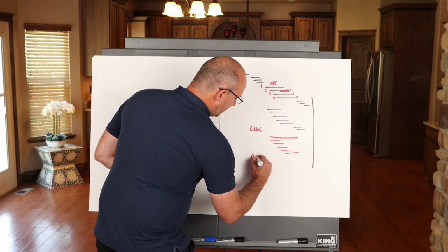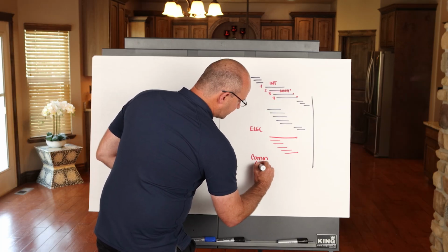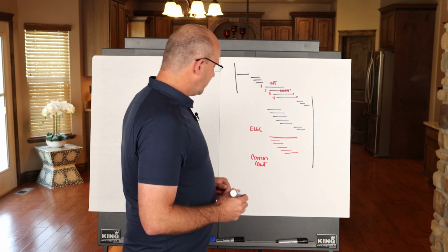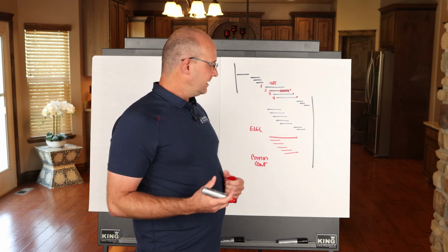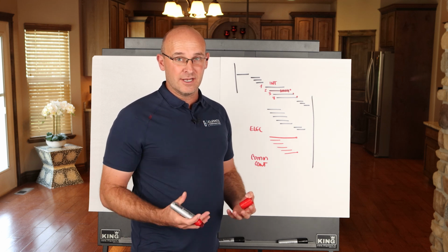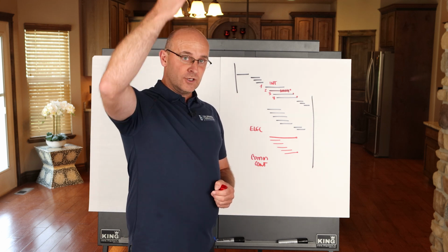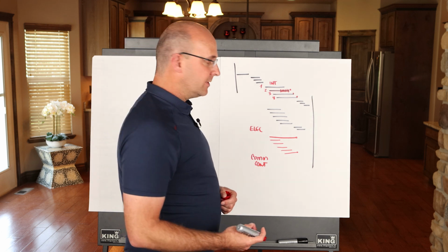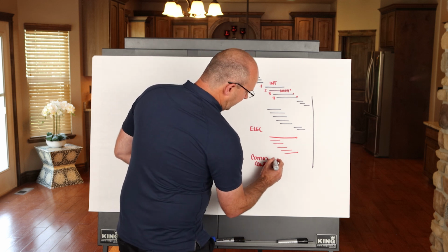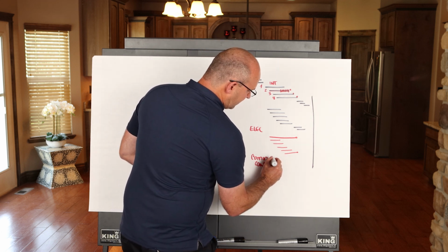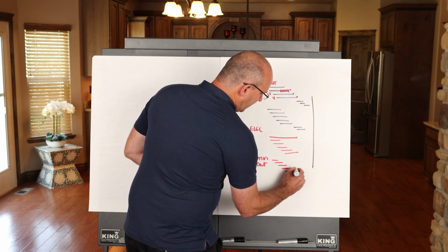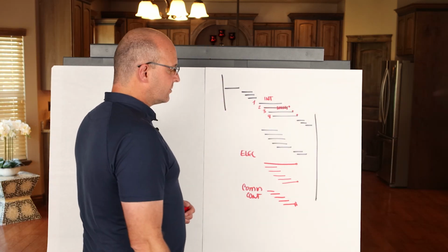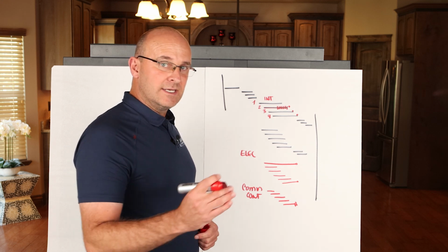Then I want to know about communications and controls. Typically you'll run your point-to-point through the overall building network, so you might need to have your racks installed and the internet up and running, or you run your controls cabling vertically through the building to connect either one. Either way, I want to make sure that the main distribution frame, the independent distribution frames, and everything for running controls throughout the project site is ready to go.